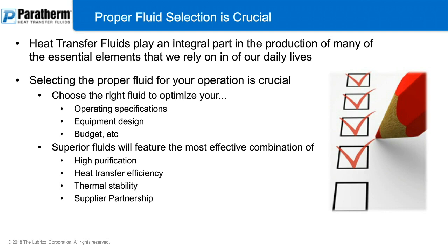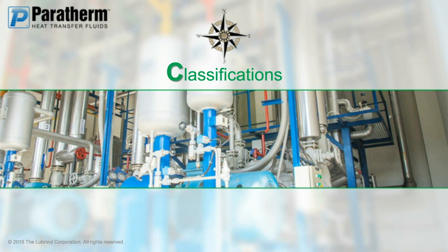Starting off with the first of the 7 would be the high-level look at fluid technology, where we're talking about classification of most commonly transferred fluids. Starting off at the bottom of this scale, you're looking at 3 different general classifications. You have aqueous-based fluids that use water as the heat transfer medium. Now, keep in mind that water is the most efficient, the highest quality, best product that you can get for heat transfer in general by theory.